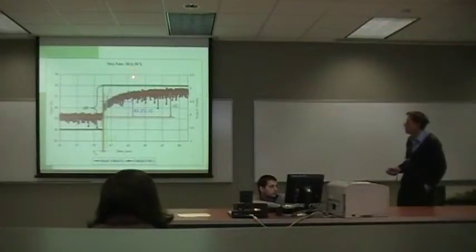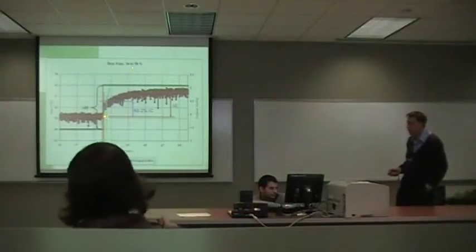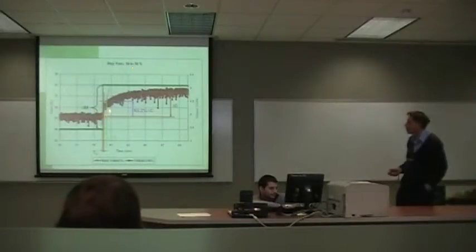Now moving on to the step function, where we have the voltage come in, the input value at 54%, and then we jump it by 11%. We wanted to see how the voltage would work. As you can see, it comes in steady and then immediately starts to rise. It gets to a steady state point. In here, we need to figure out what the T sub O, the dead time, is, and it was very, very, very short, just like 0.05 of a second.